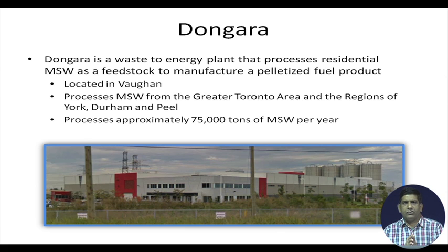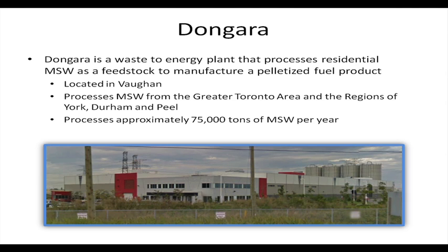They have recyclables collected separately, and wet waste going for composting or anaerobic digestion; wet waste means food waste and other organics, collected separately. And the third category is non-recyclables and non-compostables, and I should not say non-biodegradable, because even the third category may have some biodegradable waste, but it is non-compostable, non-recyclable material.